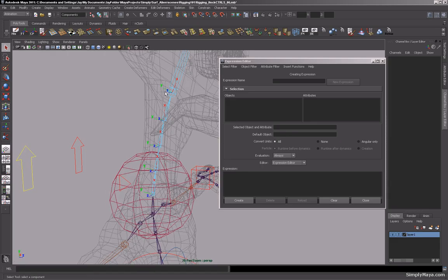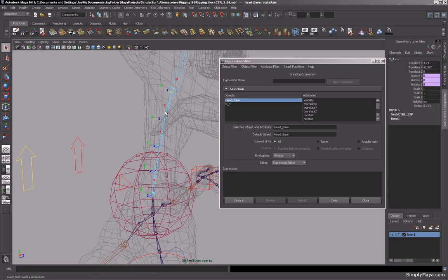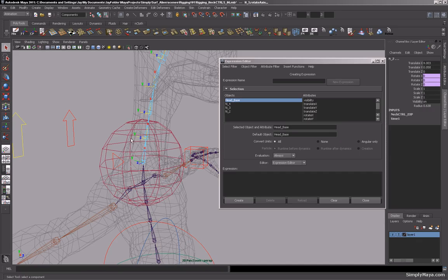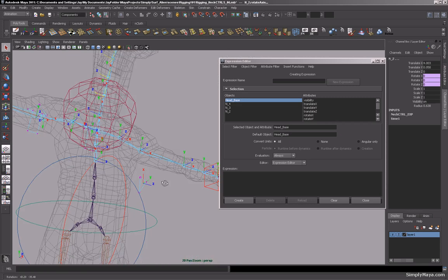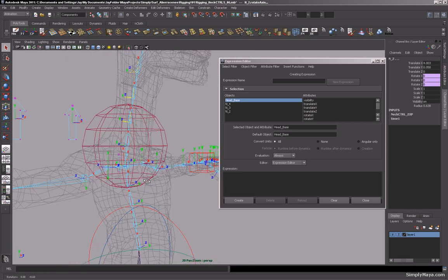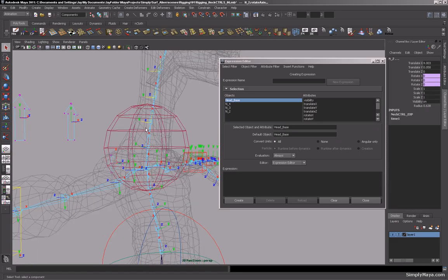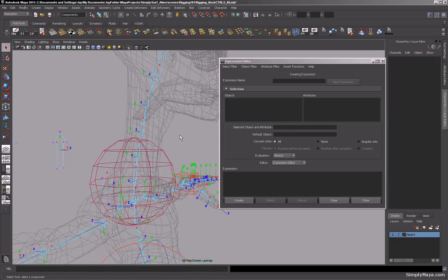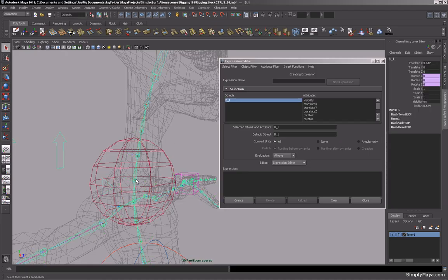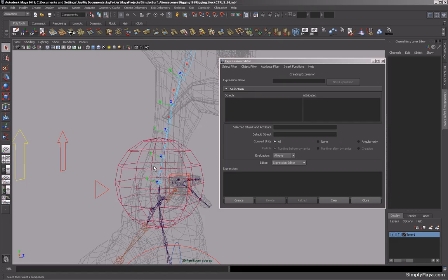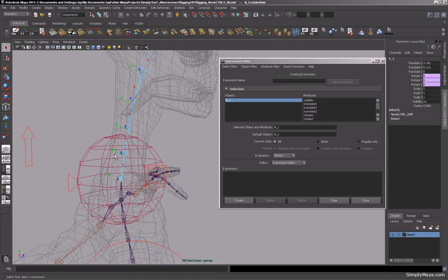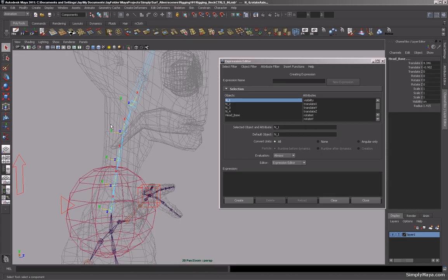And then what we want to do is grab the Y. Basically what's happening is it's all just flipped around because of the way we've drawn it. If I just select this one down here, you'll see the Y is sticking out the front on all of this. Okay, so what this means is we need to select these up here. Okay, so let's just go back to F8 and we'll start that again. Okay, so just these 4 joints, that one there as well. Now if we just hit F9, there we go, that's displaying. So again, just select, when they go yellow, you know you've got them selected, and there you go.